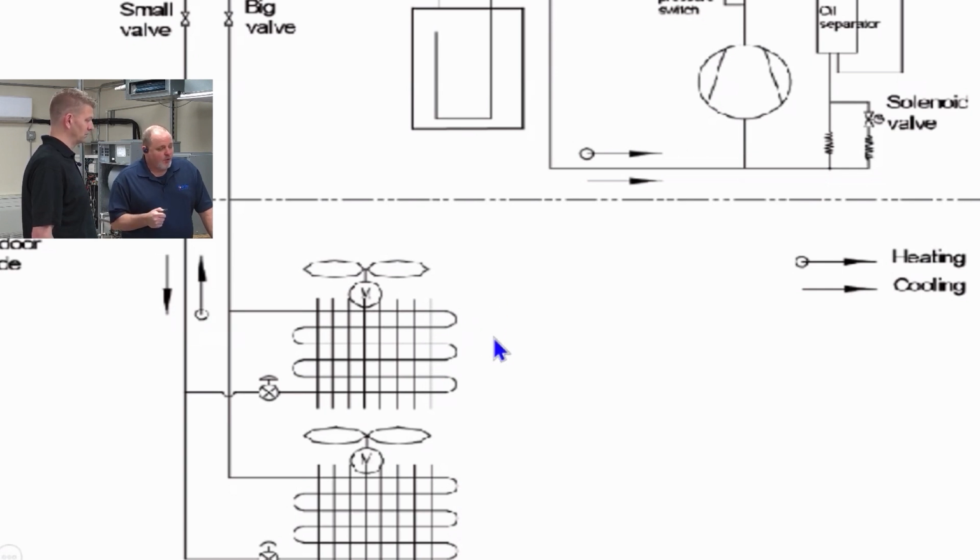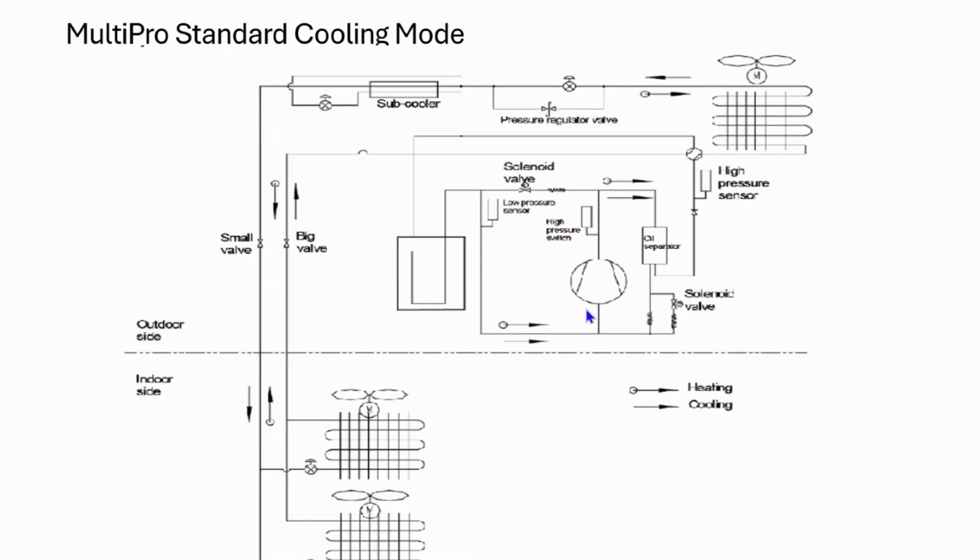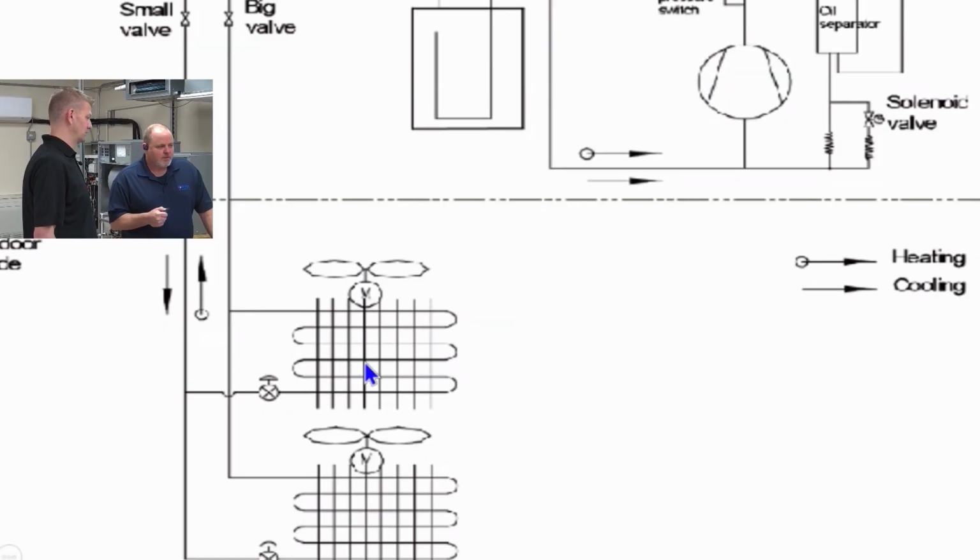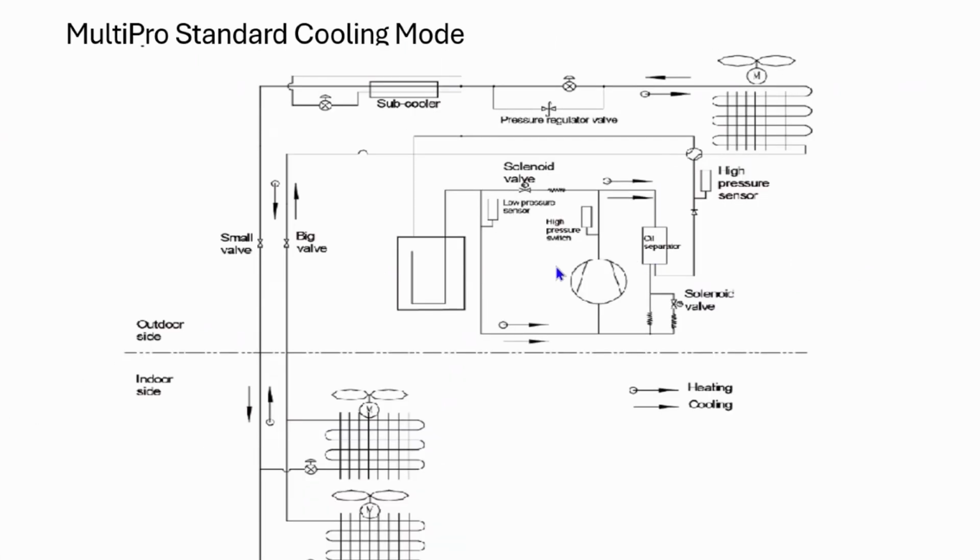And if I have 4 indoor units, the other 3 are working fine, I'm not going to get that compressor error code. But if I go in there and I shut this one down, shut that one down, shut the other one down, and leave that one on, now there's a good possibility I'm going to get a compressor error code because the refrigerant's trying to pump up against a block that it can't get through. I'm not getting my cool refrigerant gas back to the compressor. The machine's going, what is going on here? Either low pressure or high pressure fault.